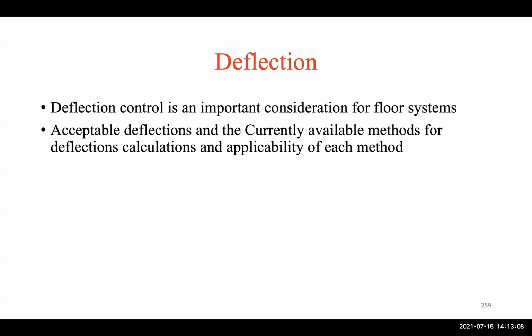Deflection is another important parameter in the design of concrete slabs in general, not only PT, but in PT it's easier, according to ACI, not other international codes. For those of you who are designing structures outside the US, the reason is because the ACI code requires the PT floors to be designed as uncracked. The U class, we call it the U class, which we talked about in the first part.